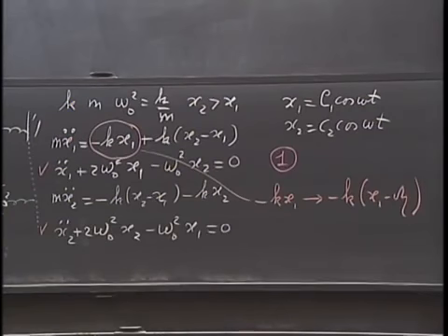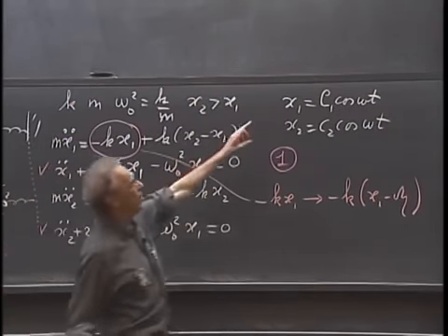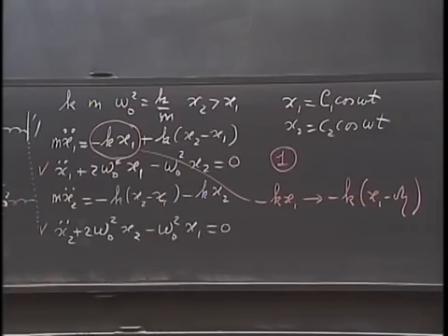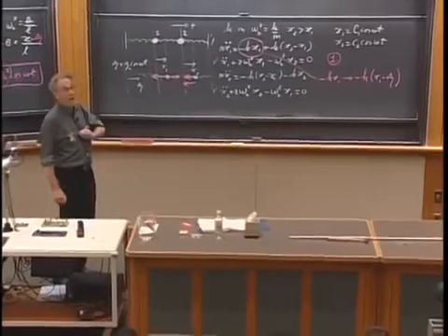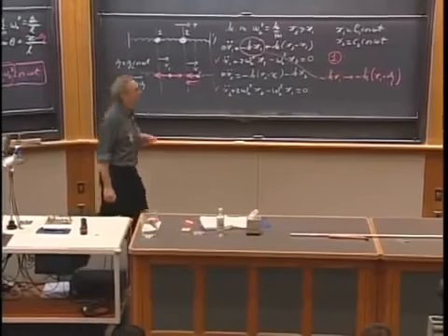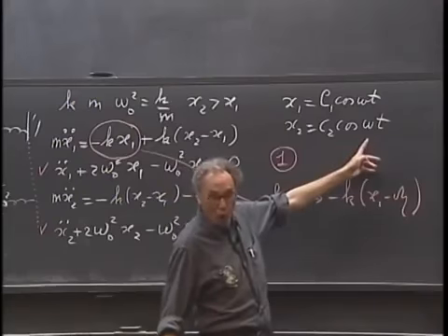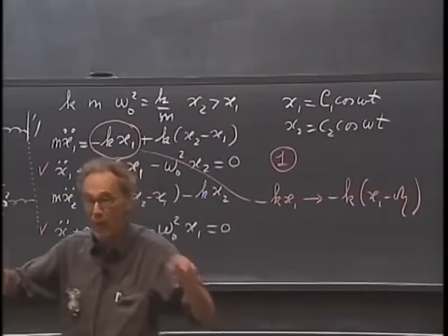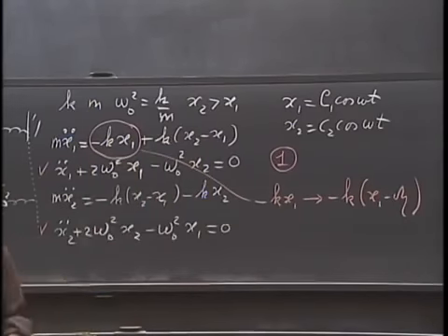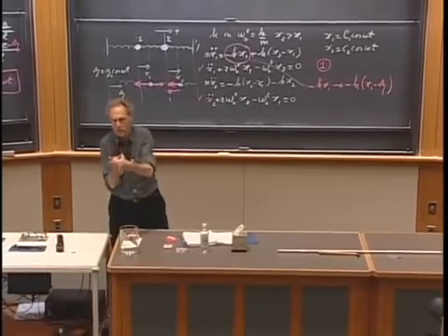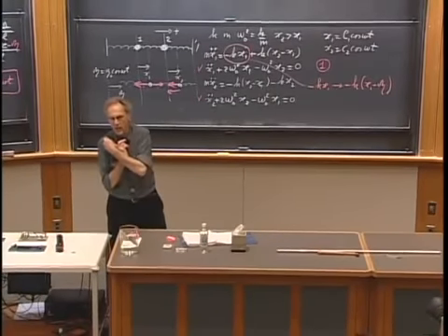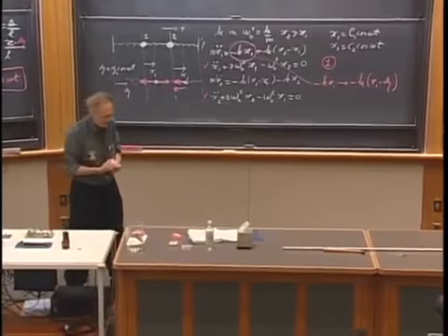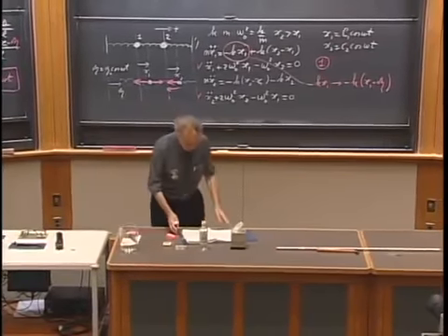But that has major consequences, of course. For one thing, if you're going to substitute now these trial functions, omega is no longer negotiable. Omega is my omega now. I set this omega, you're not going to solve for that omega. That would be an insult to me. I dictate what omega is. So that means I now get 2 equations with 2 unknowns, C1 and C2. Omega is no longer unknown. So now I get solutions for C1 and I get solutions for C2.